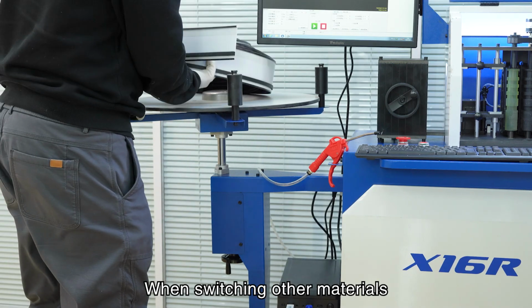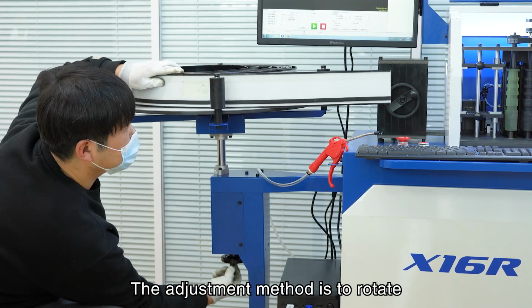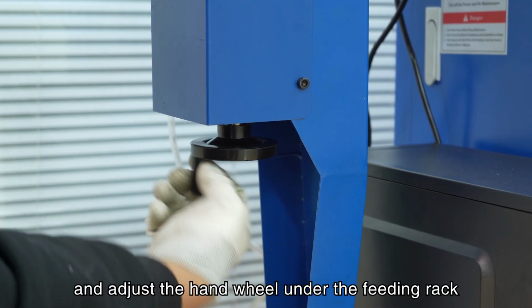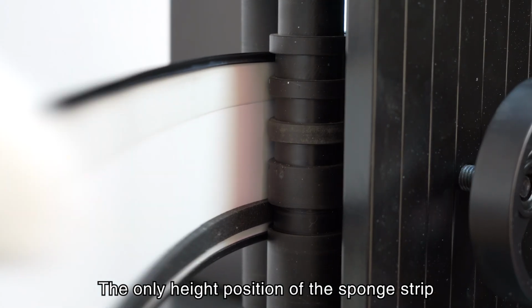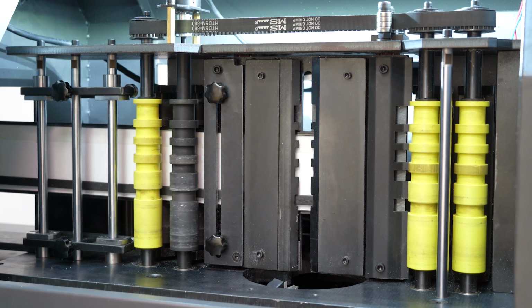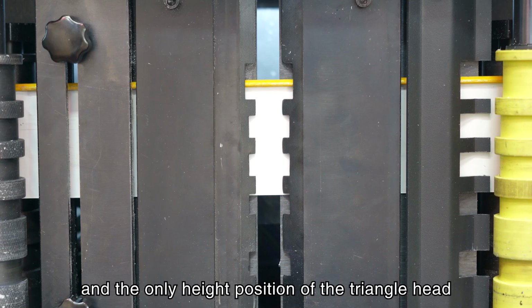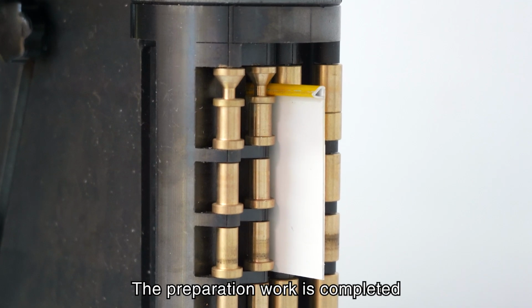When switching other materials, it is necessary to adjust the height of the feeding tray. The adjustment method is to rotate and adjust the hand wheel under the feeding rack. The only height position of the sponge strip is as shown in the video. And the only height position of the triangle head is as shown in the video. The preparation work is completed.